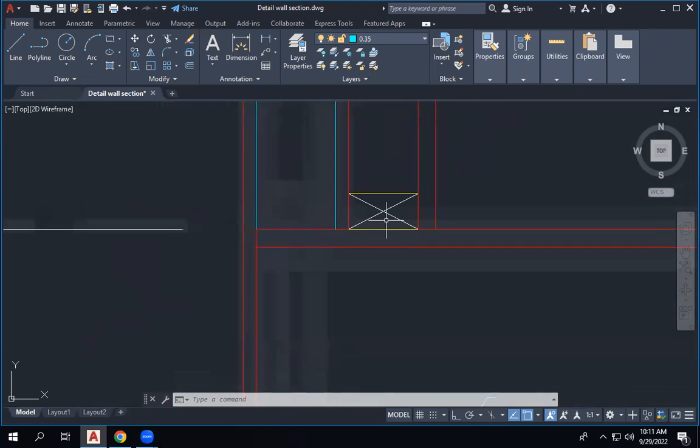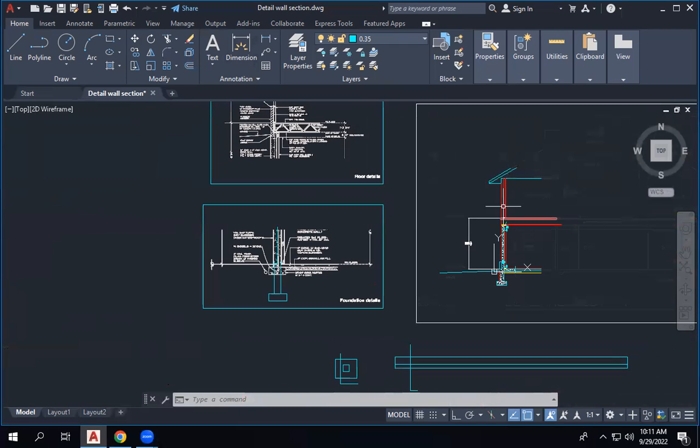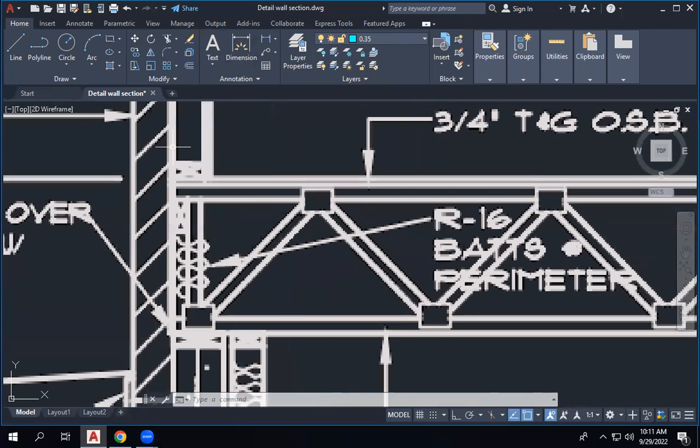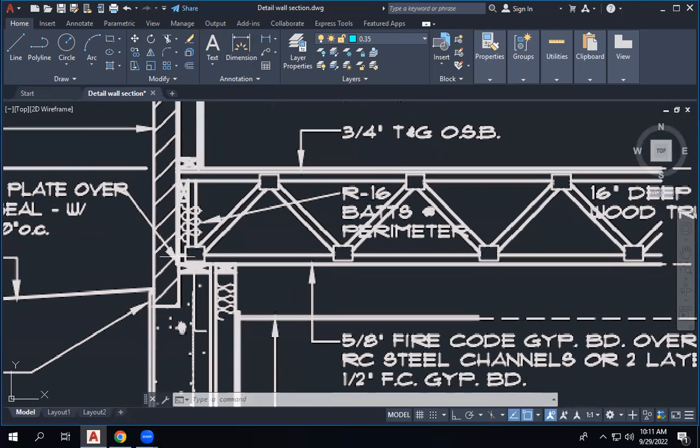Do you tell the truss? If you go to the truss detail, there's all that stuff on the left of it. This one? Yeah, right there. What should we do? No, don't do it, because now what we did was we take this truss right up to this point. So then just forget it, because this wall is wider than our wall. So what they did was, no need to get this truss right up to this point, because if this one is 1 foot, the truss will be longer than what they expected. So they stop it here and they just finish the concrete here, and they just have a brick wall to cover it up.